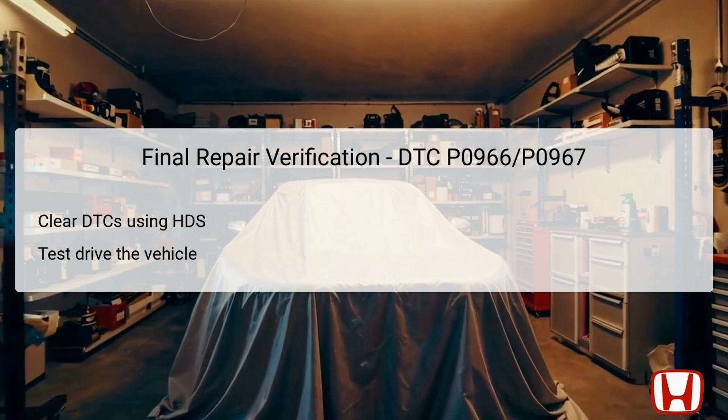Upon completing the necessary repairs or replacements based on the earlier diagnostics, the final repair verification step involves clearing any stored DTCs using the HDS diagnostic tool. After clearing the codes, it is essential to conduct a test drive of the vehicle to ensure that the transmission operates efficiently and smoothly under various driving conditions.